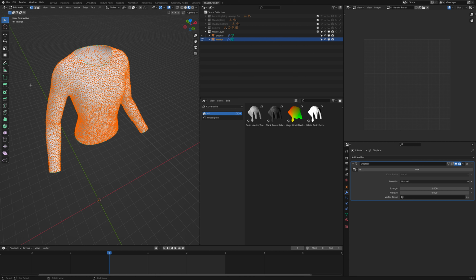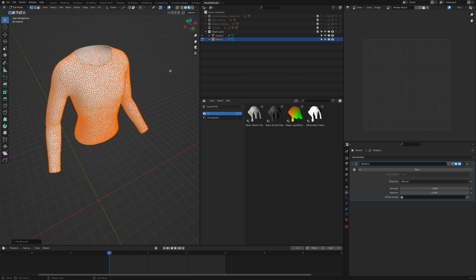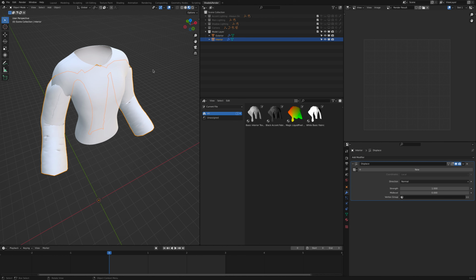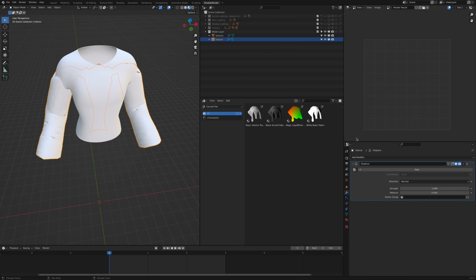So you've got everything in that one selected. If not, you can just hit A and select all of it. And then go to your Mesh, go to Normals, and click Flip. Now it doesn't look like it actually did a darn thing, but when you hit Tab again and leave edit mode, you can see now the shape is a little different.